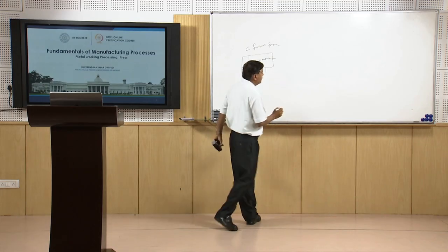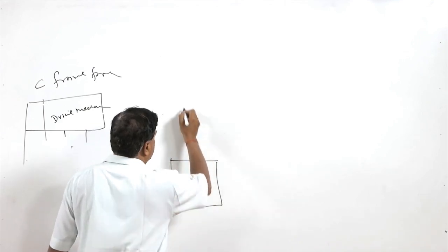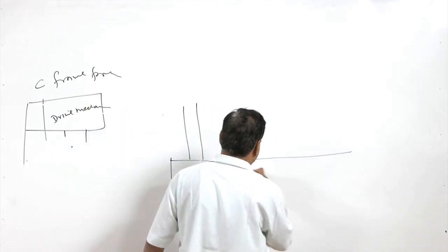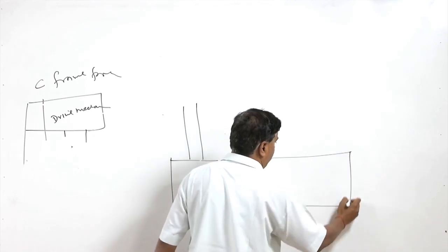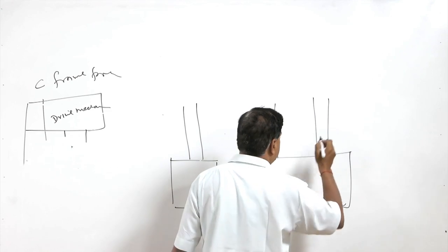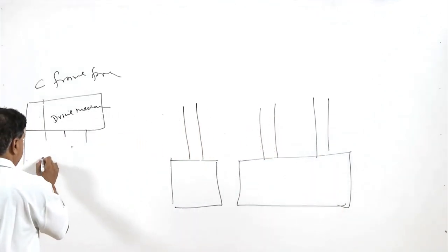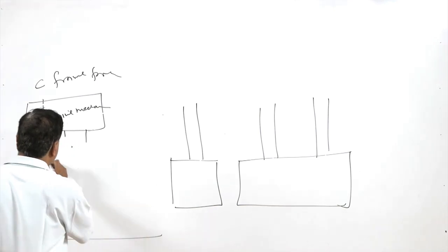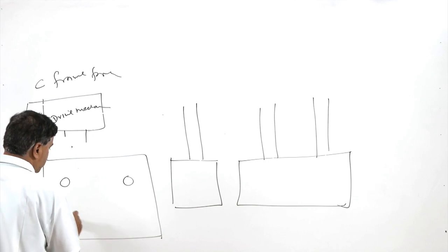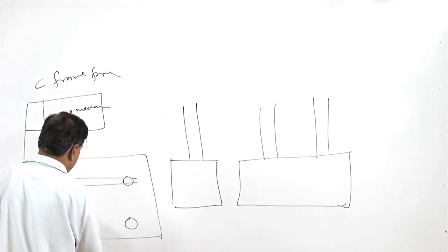If the ram is smaller in size, then just one point of suspension is applied. If the ram is very wide, then it can be suspended with the help of two connecting rods like this. In the top view, if the ram is not just wide but also long, then it can be suspended using four connecting rods, which will be powered through two crankshafts.